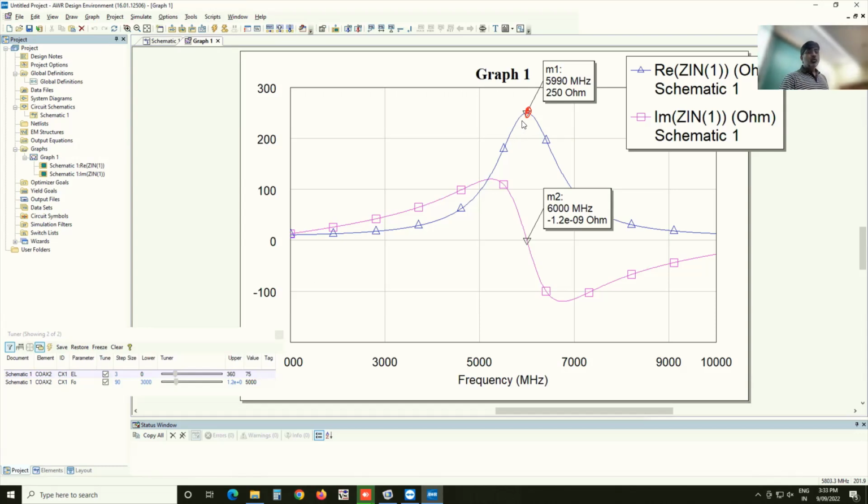So in order for you to have a flatter response, you cannot just use a single quarter wave transformer. You need to do something more sophisticated. And maybe we can see an example of how that would work. So I was basically asking you, what is it that determines this match? This depends on the transmission line and also the impedances you're matching.